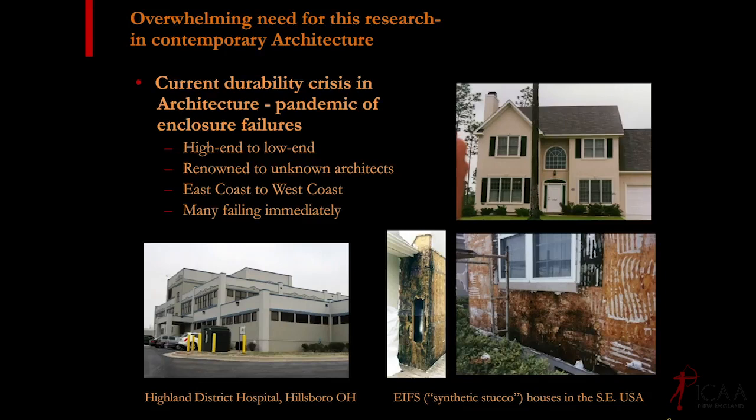And I think we're really in the midst, as a design and construction community and profession, of a crisis of durability. Whether you're talking about lousy McMansions on any old cul-de-sac, USA, these are from the east, or synthetic stucco failures in the southeast. As a young engineer at SGH, I spent a lot of time in North Carolina and Georgia investigating failures like this that were all on buildings less than 4 years old. A lot of times they were only a year or two old, and the sheathing was basically turning into mulch and these buildings were falling apart.